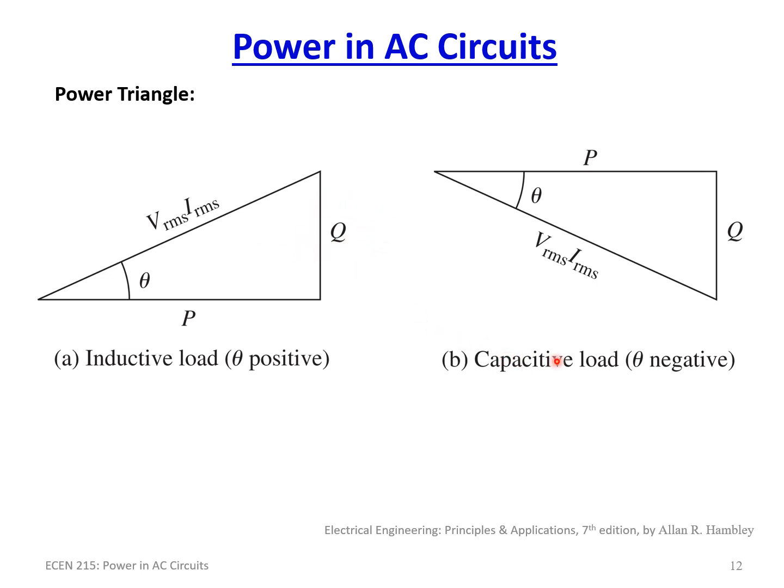And if you have a capacitive load where theta is negative, that's a case where the voltage is, say, 10 degrees, but the current is leading in theta. So say we had 10 degrees, but the theta in the current was 20 degrees. And so now we have a power angle of minus 10 degrees.